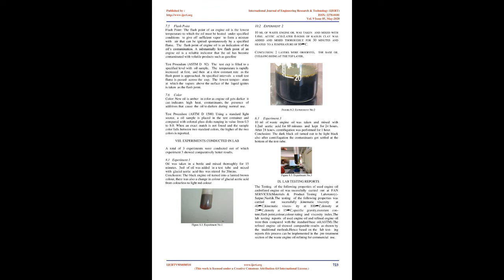7.3 Moisture content. Moisture is generally referred to as a chemical contamination when suspended in engine oils. Water created in engine oil is a result of absorbing moisture directly from the air. Oil is hygroscopic. Sources include condensation, humid air entering oil compartments, corroded or leaky heat exchangers, and combustion. Fuel combustion forms water which may enter the lubricant oil through worn rings, oxidation, chemical reaction, and neutralization, when alkalinity improvers neutralize acids formed during combustion, and free water entry during oil changes.